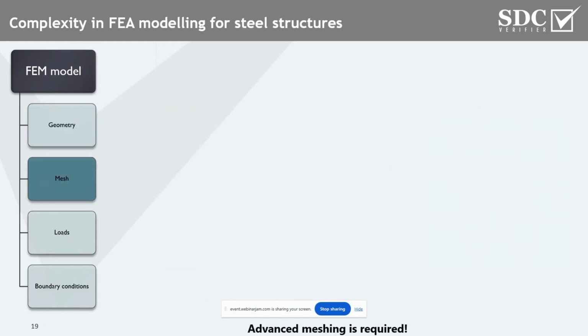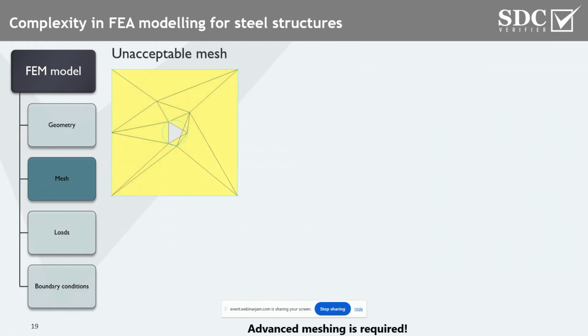And if we go to the mesh creation, that's also a tricky thing, because there are different solutions available nowadays, but it is very important to understand and to have all the tools to make this mesh at a good level. For example, in this picture, you see a definitely unacceptable mesh. Yeah, so you have stiff elements, you have not enough elements along the edges, and that, of course, all influences your results.